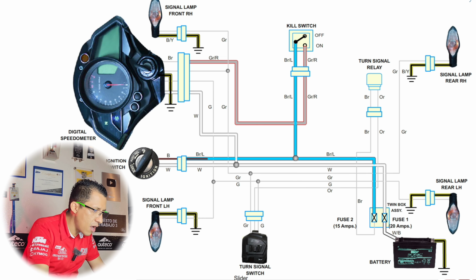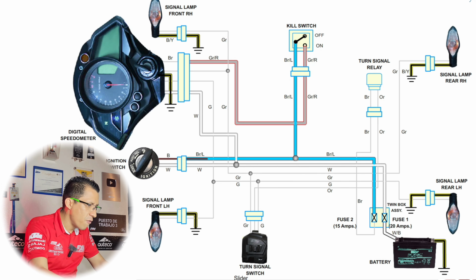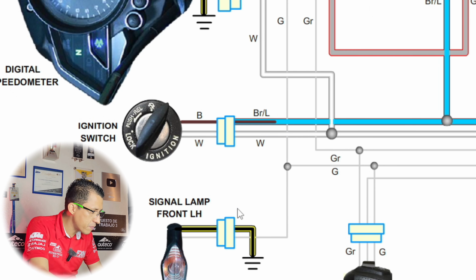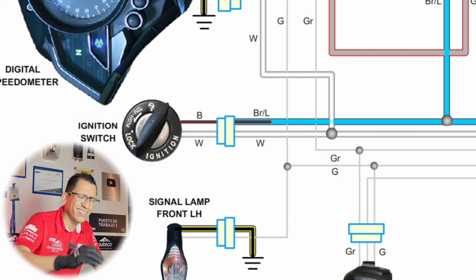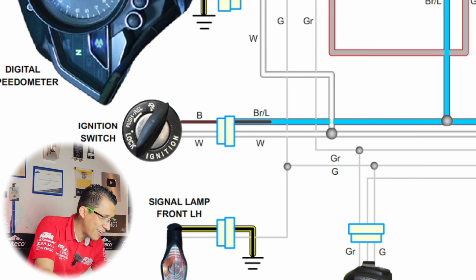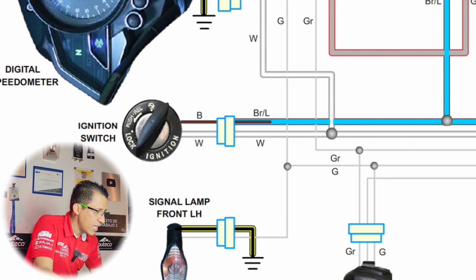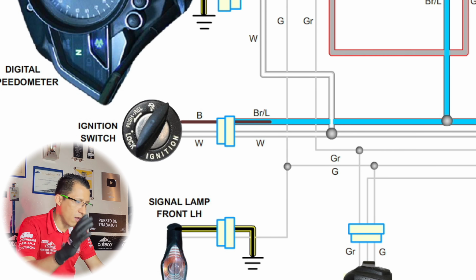In diagrams and on motorcycles, it is very common and very normal for the wires to change color. What does it mean? See that here in the switch it is black, but then it changes to a brown with a blue stripe. So it is normal for them to change color. It is very normal. After a connector, that can happen. Usually in the manuals, they give us this information. However, if not, a specific follow-up must be made for each component.